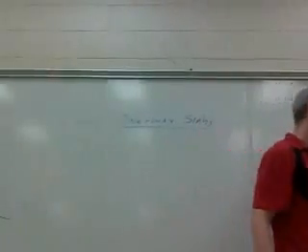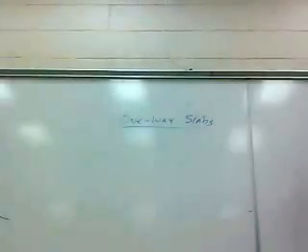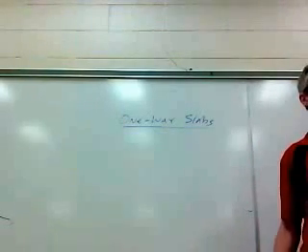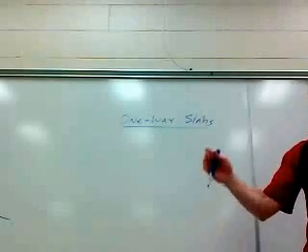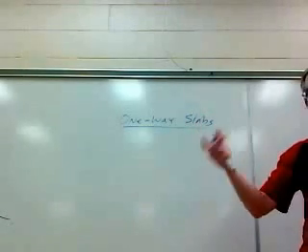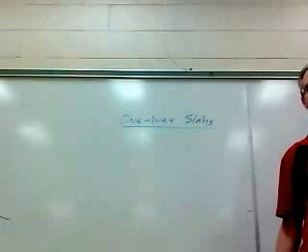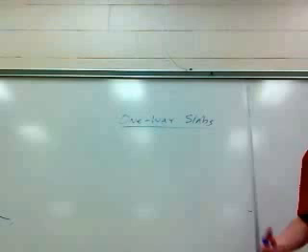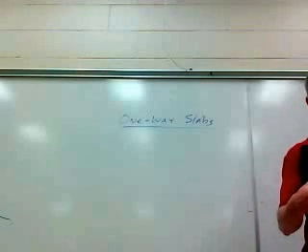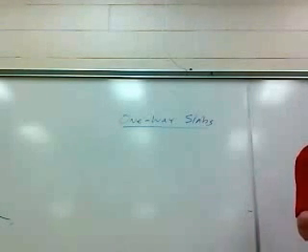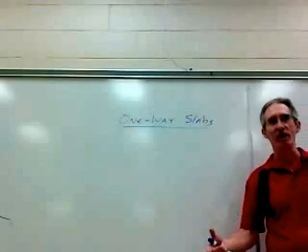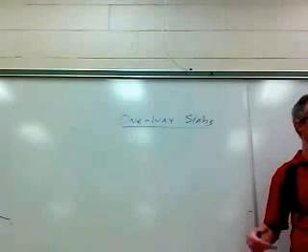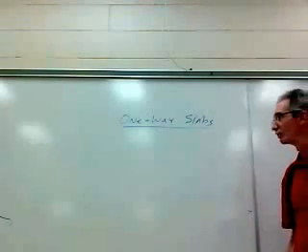Like I said in our talk about framing plans and just framing of concrete buildings, the floor system, the beams, the columns, they're all monolithically cast. I mean, you'll have the beams that are literally framed. The concrete is poured, so it's all in one with the column. It's all in one with the floor slab, and so on and so forth. It doesn't have to be that way, but that's generally the way it works.